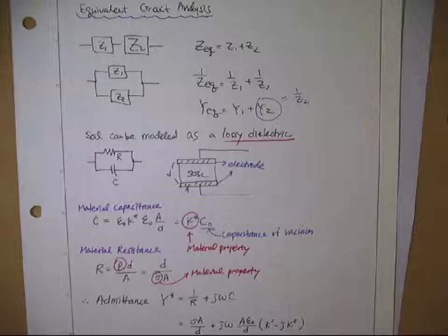So you have an R and a C, and this R and C value will be converted to the permittivity and the electrical conductivity value of the soil. So we're going to see that on Tuesday, and how we can calculate the real permittivity and the imaginary permittivity from the measurement. And then probably I'll show you how to use this one too.